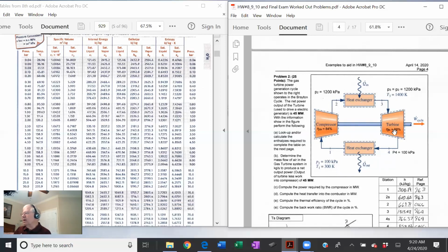And then it goes to the turbine. Now we use the ideal gas equations for air through the whole process, even though there's a little fuel involved in here, and after the combustion process, there are some different chemicals formed. But believe me, the properties of this process after it's combusted are very close to ideal gas of air, and the air analysis is strictly straightforward and accurate.